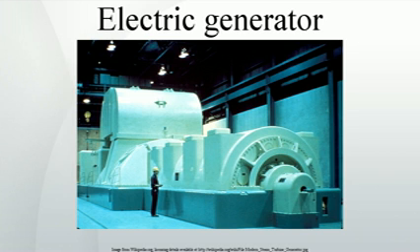Vehicle-mounted generators. Early motor vehicles until about the 1960s tended to use DC generators with electromechanical regulators. These have now been replaced by alternators with built-in rectifier circuits, which are less costly and lighter for equivalent output. Moreover, the power output of a DC generator is proportional to rotational speed, whereas the power output of an alternator is independent of rotational speed.